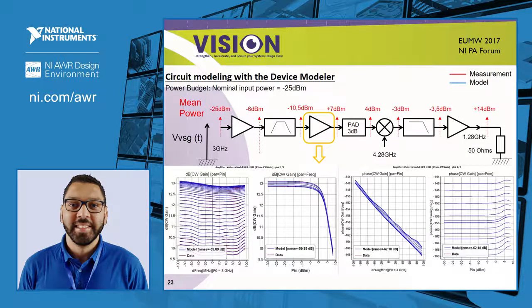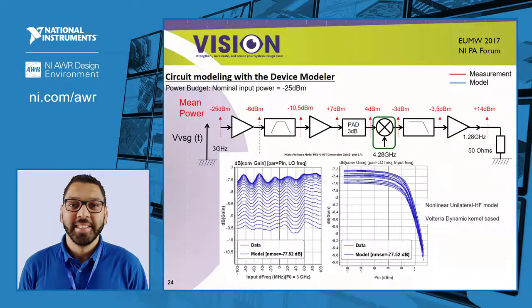The second amplifier doesn't exhibit low frequency memory effects. The model will only take into account high frequency memory effects, and it consists of approximating AM/AM and AM/PM measurements at several frequencies. We observe an excellent approximation by the model. The advantage is to be able to use the most suitable model and not oversize the measurement bench.